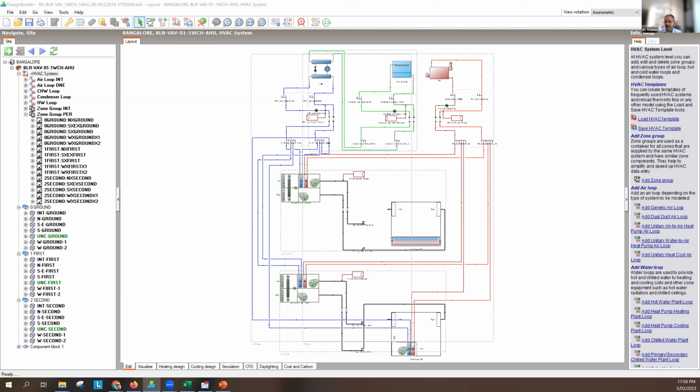So I would encourage you to start thinking about direct emissions from refrigerants as well. In some European countries, they are now banning direct expansion systems beyond a certain capacity for two reasons. One, this direct emission, and number two, because there are concentrations of refrigerant in the occupied space, and they're not really healthy for you. Okay, they're not really poisonous either, but they're not particularly healthy for you.